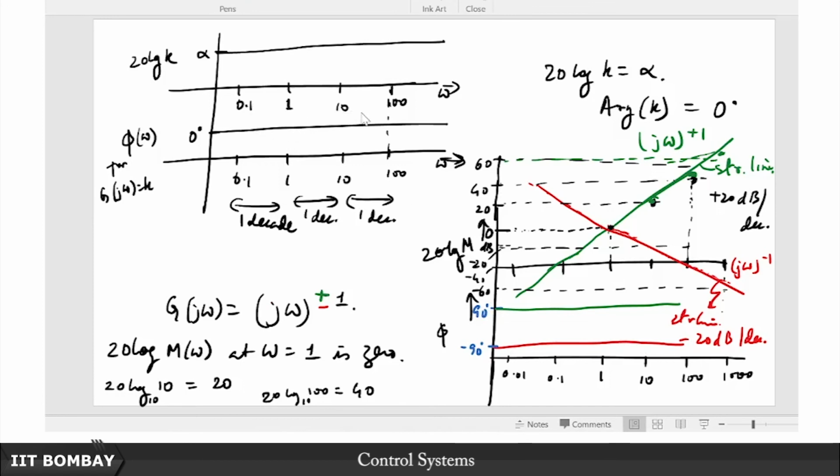So it's very easy. In other words, if the DC gain is increased, you can immediately see that the overall Bode plot will rise. If the DC gain is decreased, the overall Bode plot falls. Later on we shall see some outcomes of these, and there is a way to interpret all of these consequences insofar as stability is concerned.